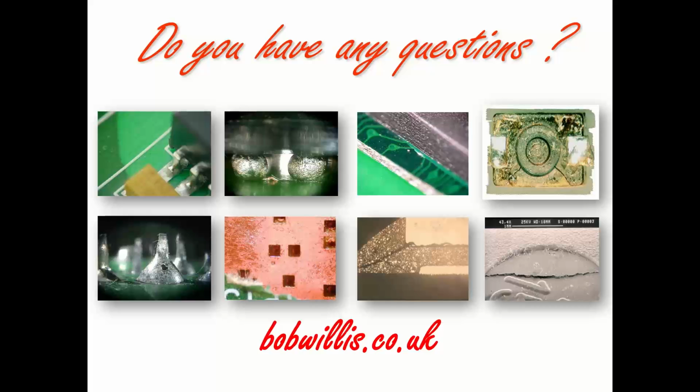Next question. In terms of tape and reel, can I bake? Again, it's something you've got to speak to the supplier about. Most of my experience with trying to bake tape and reel components is that the peel strength characteristics of the cover tape changed, and it always tended to cause problems. Now, with the technology changing as it does on a regular basis, speak to your supplier. What temperature is he comfortable with you baking at? But remember that it needs to be over 100 degrees Celsius to actually get the moisture out.